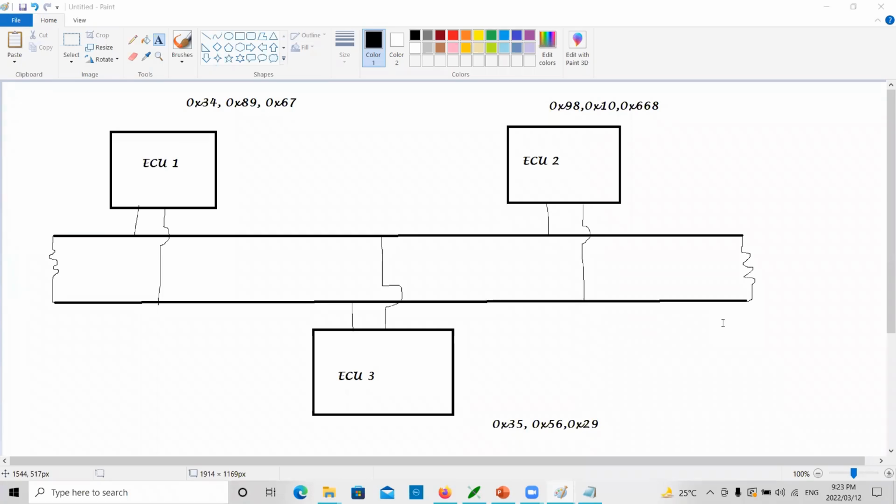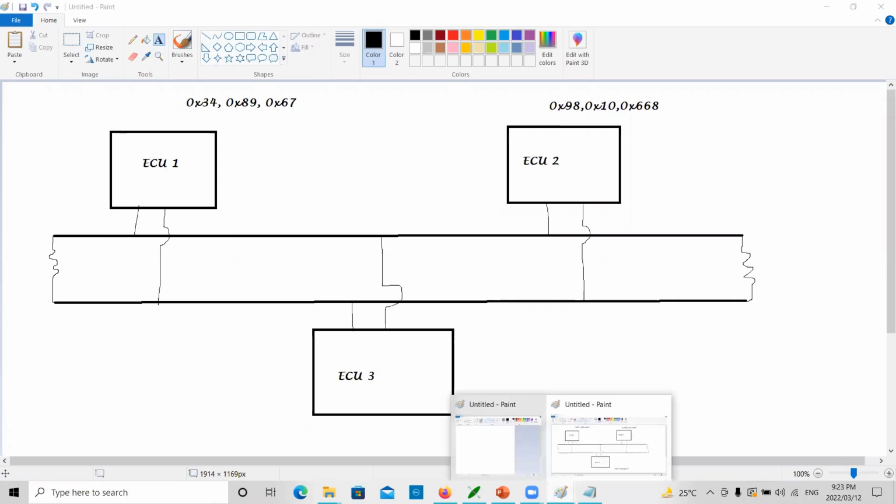Yeah. Yes. In a car, we will have multiple CAN buses. That is because we have channel 1, channel 2, like that. They maintain separate channels. Though both channels operate in CAN, they are 2 different channels. Why don't we connect all the ECUs in one CAN channel, one CAN bus itself? They used to have high speed CAN, low speed CAN, mid speed CAN. Why is it so?